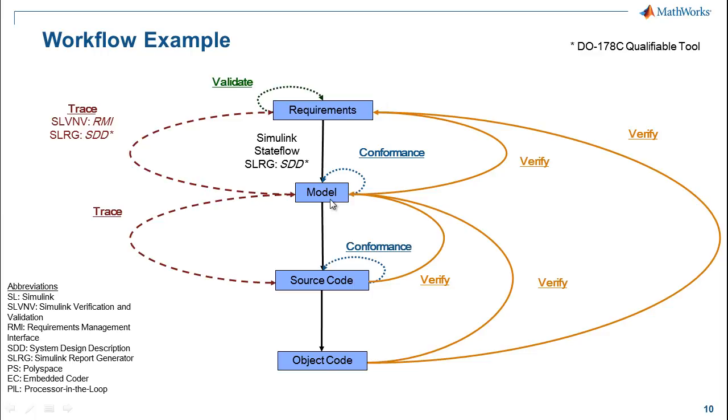So within Simulink, what this typically means is just ensuring that everyone who's building Simulink models is using things like the same solver options, the same sample times, the same diagnostic settings. And then more subtle than that, and kind of more user-specific, would be using the right block constructs with the right options. And so that's part of the modeling standard.